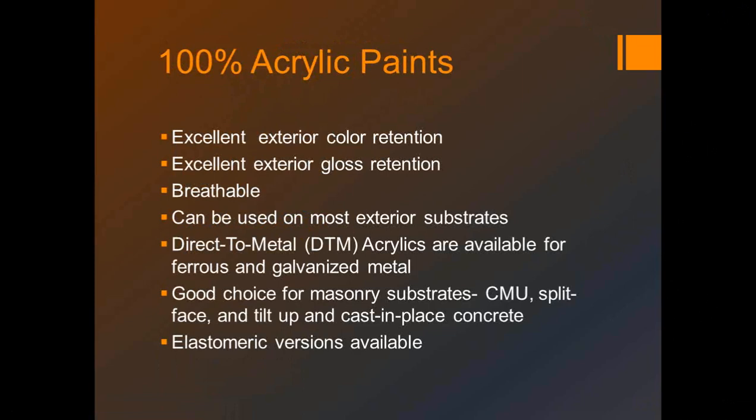And the vinyl acrylics, again, will give you the wider range of sheens, can get to dead flats for interior paint. But I would be a little cautious, actually a lot cautious, in using those in an exterior environment, because a vinyl acrylic paint can chalk on you in an exterior environment, where that's not something you normally have with 100% acrylic paint. Chalking is not a common factor with 100% acrylic paint.